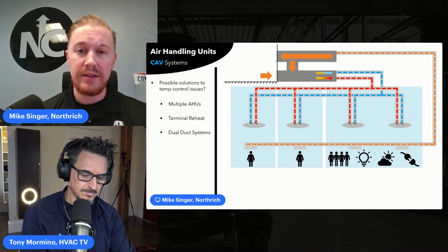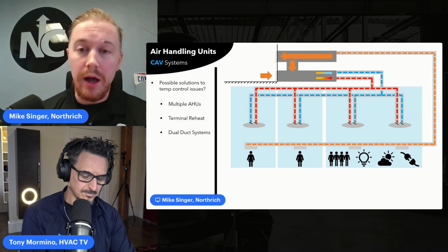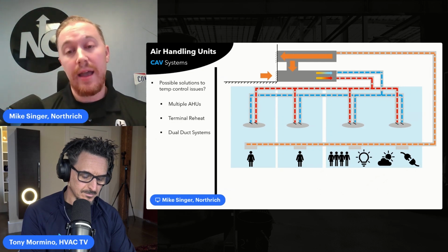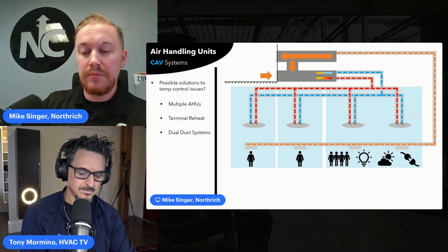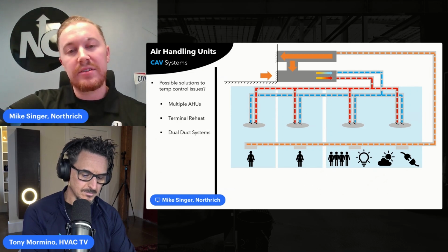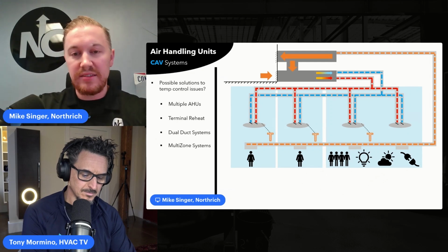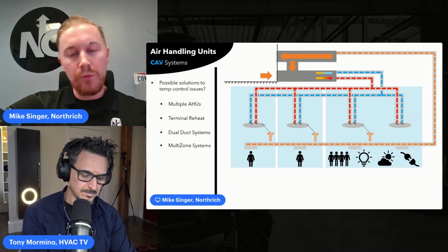Those 2 supplies have a hot and a cold side. So I might have a hot air duct delivery system and a cooled air delivery system, and I'm mixing at the terminal, which each have their own thermostats tied to them. Okay, so we'll still see these.